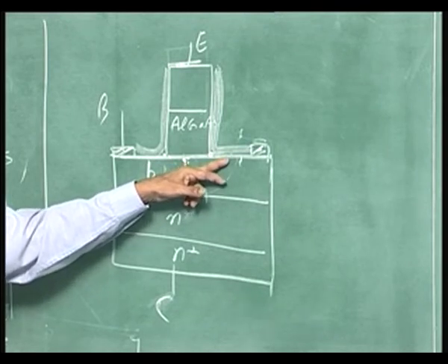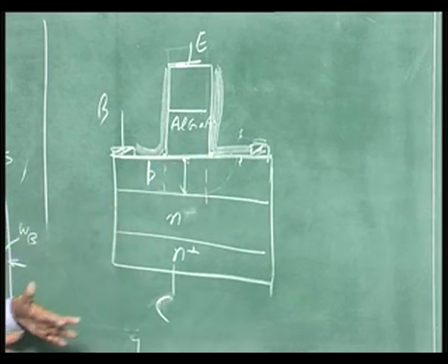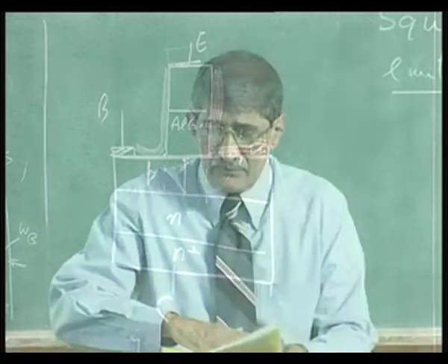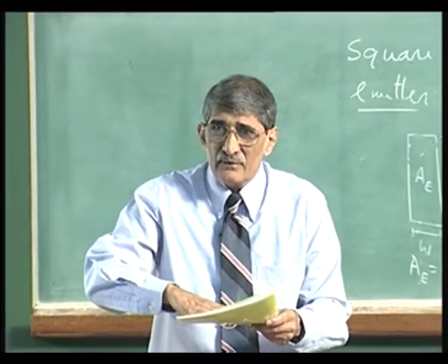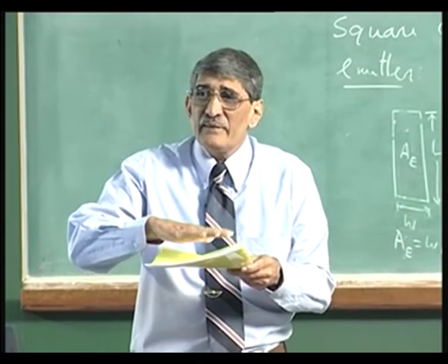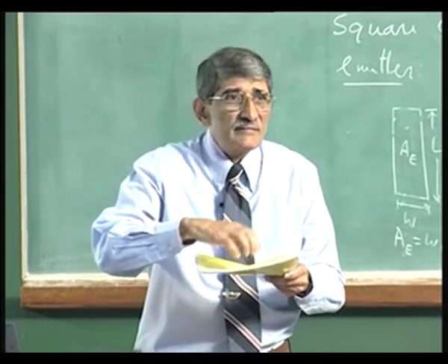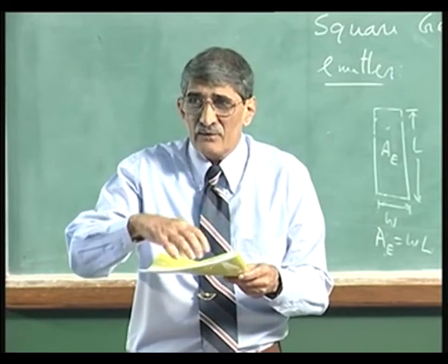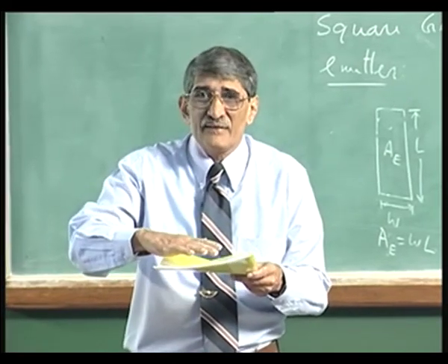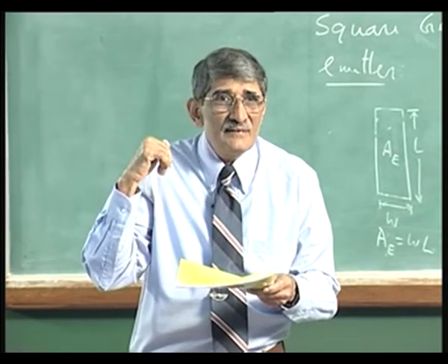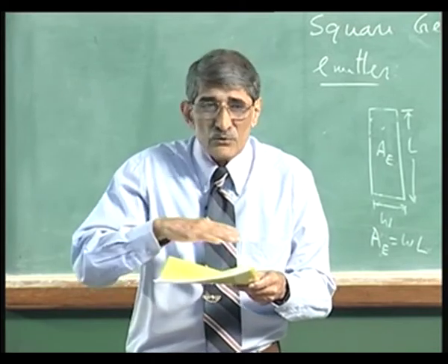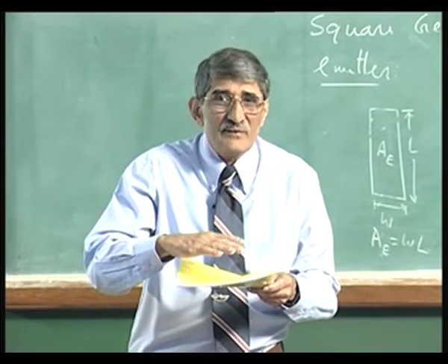You do not get good passivation, because if you have a surface and you want to satisfy those dangling bonds, the deposited layer must be in intimate contact with the surface. It should interact with the dangling bonds. Some sort of chemical reaction should take place for the surface to get passivated. When you grow silicon dioxide, it is a native oxide. Silicon is converted into silicon dioxide. So, those dangling bonds are wiped out because of the SiO2.